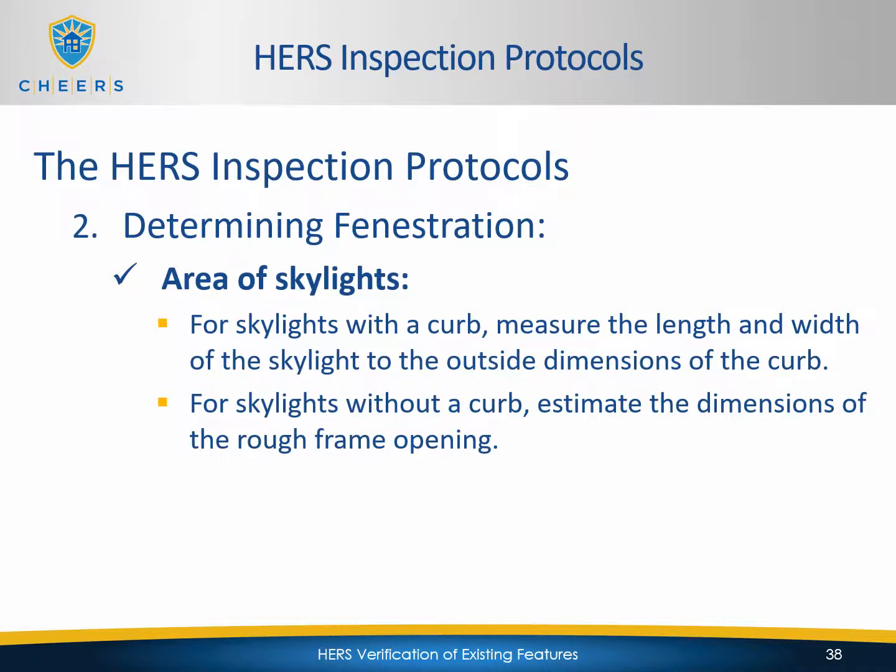For skylights, you definitely want to define the area of the skylight. So for skylights with a curb, measure the length and width of the skylight to the outside dimensions of the curb. For skylights without a curb, you want to estimate the dimensions of the rough frame opening.